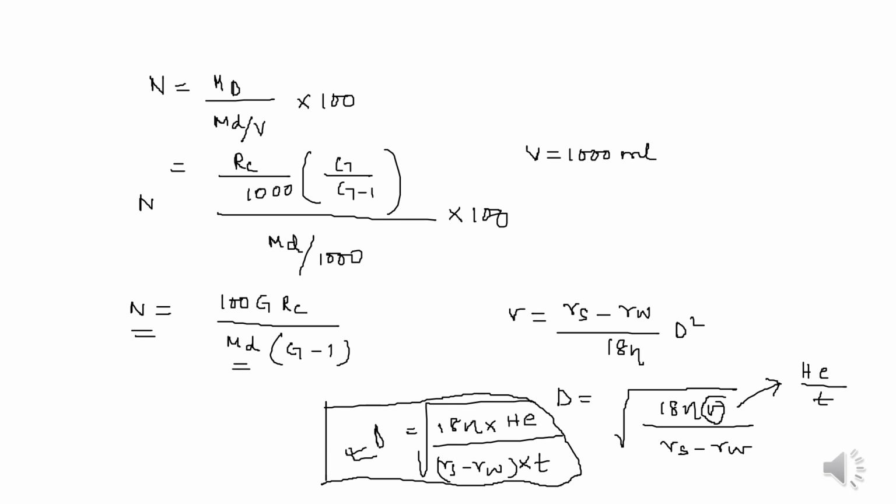So in this, what we can do is, for different diameters of particles, we can determine the percent finer than that of the particle size d, and accordingly plot a grain size distribution curve, having the N or the percent finer on the y-axis and the diameter d on the x-axis. So this grain size distribution curve is usually drawn collectively when we do the combined analysis.